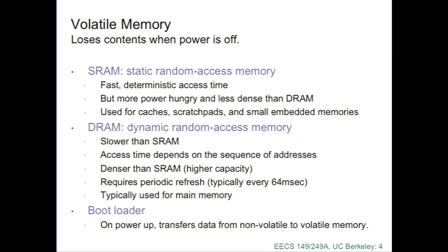Now, one of the conundrums that you face as an embedded software designer is you don't generally know how the memory addresses are mapped onto the physical memory. And on top of that, you don't know how your compiler is allocating memory unless you look at the output of the compiler, disassemble the assembly code, then you can look at how the memory all got allocated, and then you can tell. But who wants to do that? So you really have to dive very deep into the software that the machine is actually running if you want to understand the timing of the memory accesses.